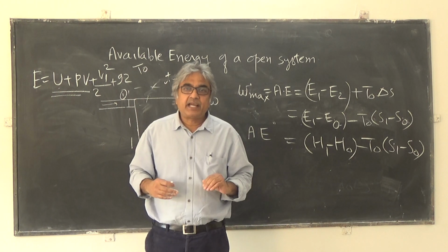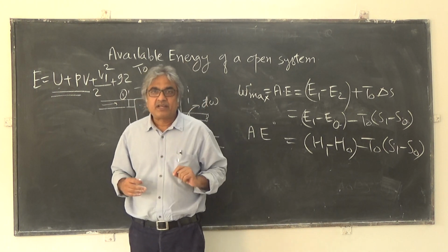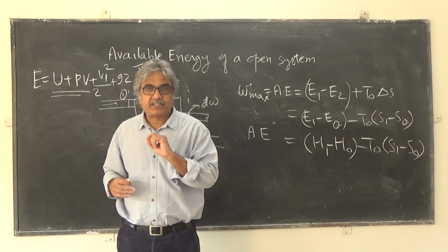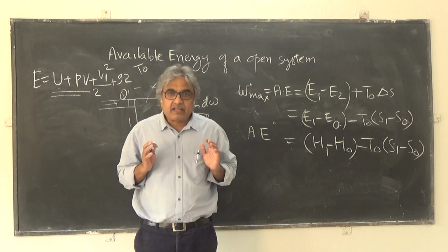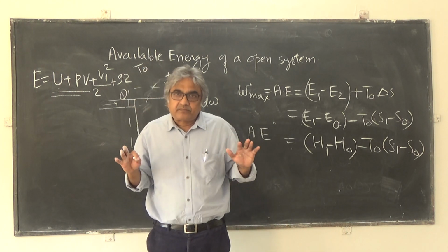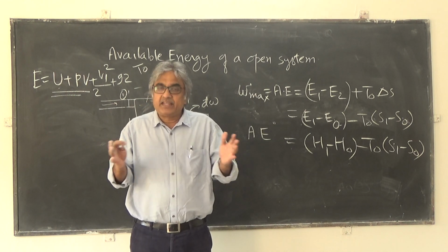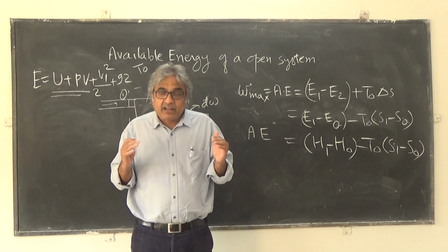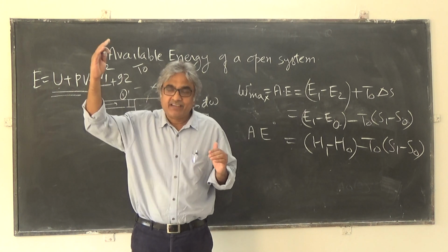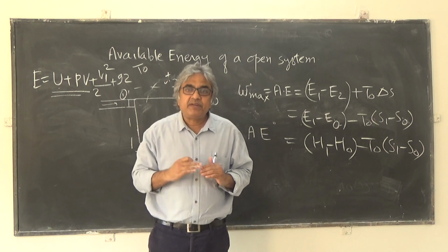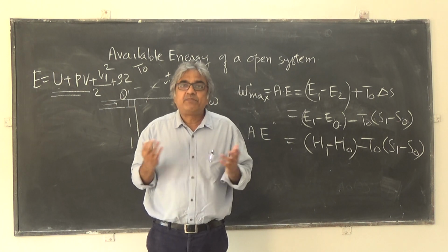Now we are introducing an interesting concept, and it's called second law efficiency. Now we will compare the actual efficiency of any heat engine to that of an ideal engine, which is also working between the same temperature limits. Okay, that means a Carnot engine.